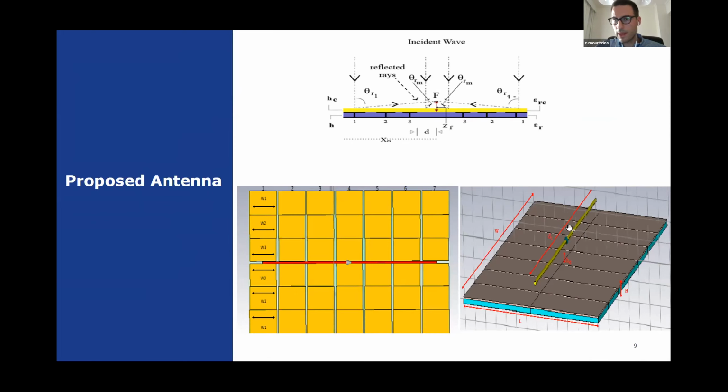And with a dipole placed on top of it, it was taken into consideration in order to resonate at this frequency. And actually, it was our initial goal to make the structure resonate at this frequency and actually maximize VOC at this frequency. And later, the matching network was designed based on this structure in order to provide matching at this frequency.